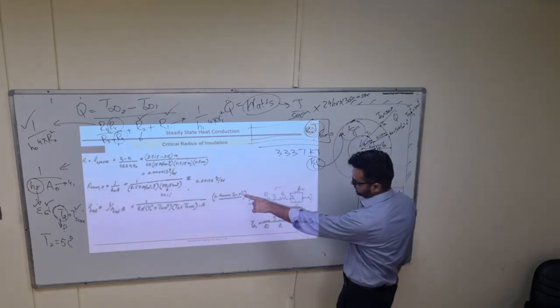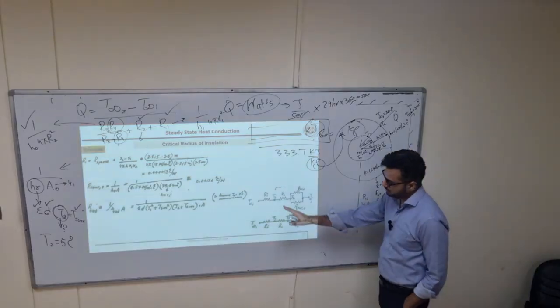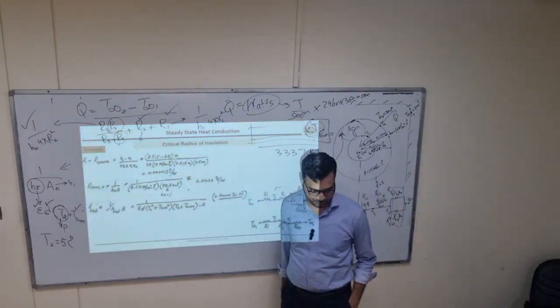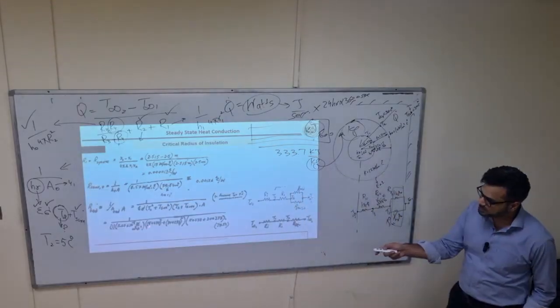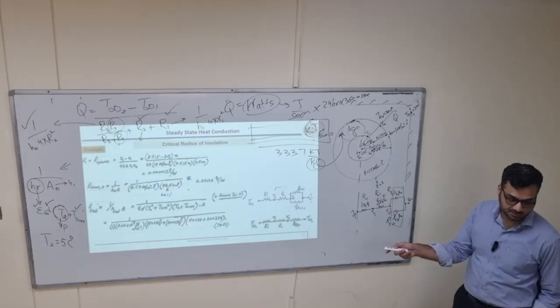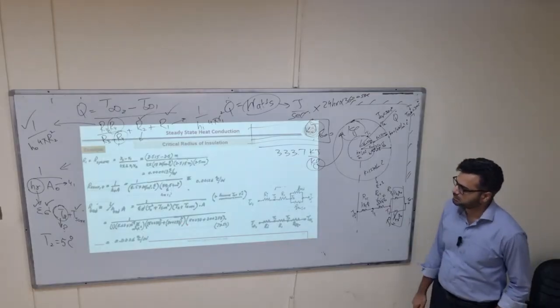Here we have assumed T2 as 5. And here again, always remember, it's not delta T, so temperatures must be in Kelvin. 5 plus 273, T surrounding is 30, 30 plus 273 squared. It's not delta T, okay, the radiative part.